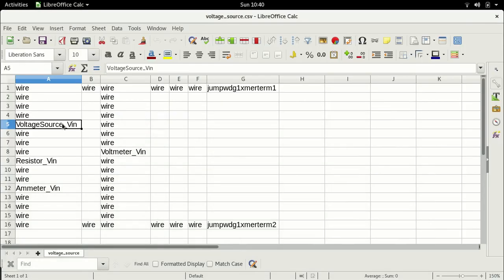What we're going to do is, instead of just increasing the frequency to 1000 Hz, I would like to emulate what actually happens when you connect a converter. So for example, when you connect a converter, you have a switched voltage, right? You have a rectangular voltage whose pulse width changes. That is how any power electronic converter works. We adjust the pulse width so as to adjust the output voltage, right?